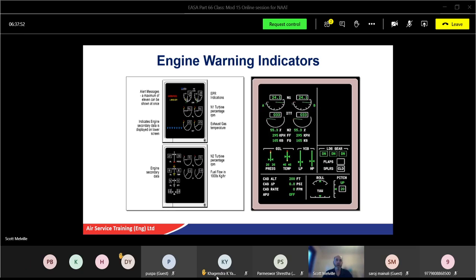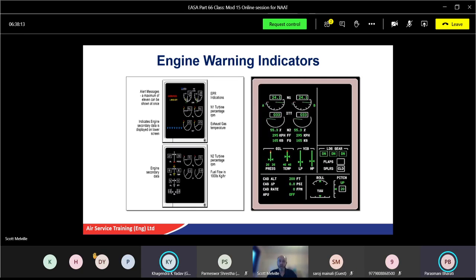We also find one in the CVG system as well. What was that electrical component? Four letters. LVDT. Yeah, LVDT, linear variable differential transformer, in this case. That'll send an error signal. If the gimbal is out of balance, it'll give an error signal to the potentiometer at a specific rate, which will move your gauge.